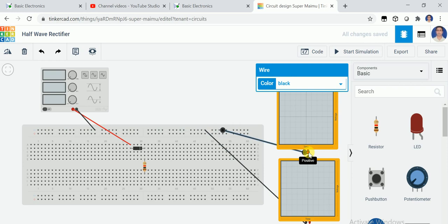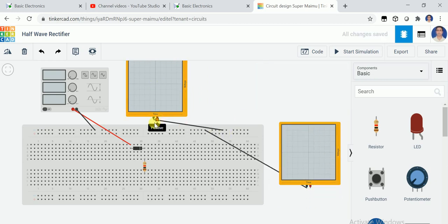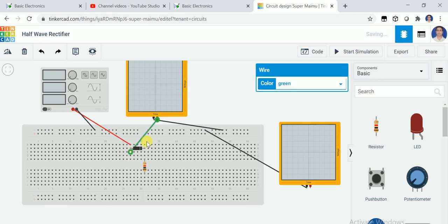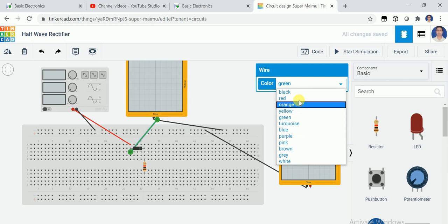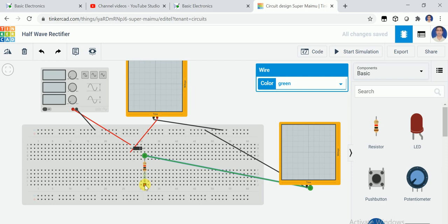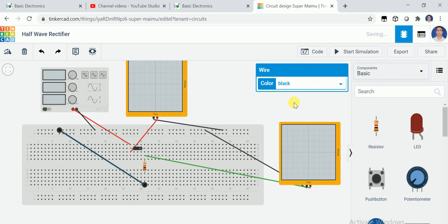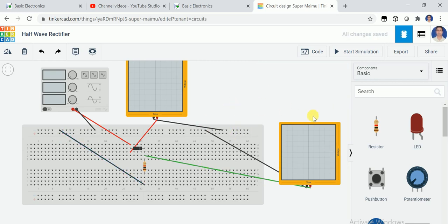In this red section, the first thing we require is to connect at the input. So the first oscilloscope should be connected as the input. Just connect this at the input. This is my input oscilloscope, and this other one should be connected through the resistor. But the resistor is not grounded yet, so we have to ground it by connecting it to any point on this line. It will be grounded. Now the circuit is completed. Though it looks quite complicated, the circuit is simple.